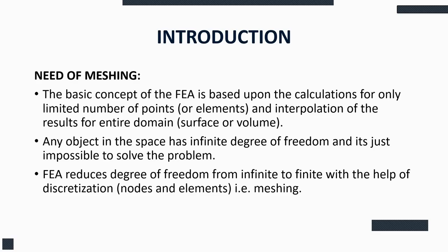FEA itself says finite element analysis, so you are required to cut down the whole geometry, whole surface or whole volume into a small number of pieces like elements, and the connection between two elements is a node. Means you have to convert your whole body into elements and nodes. Then and only then you get the exact result to the problem.